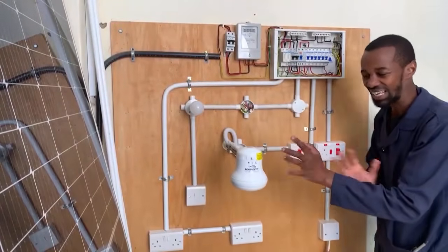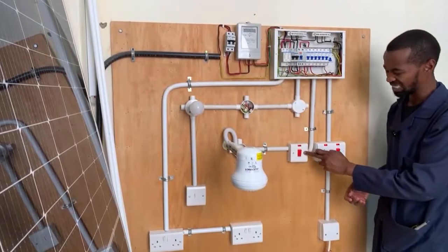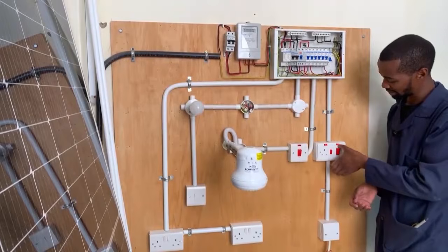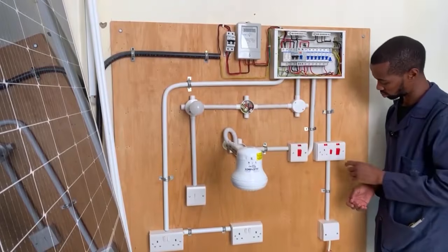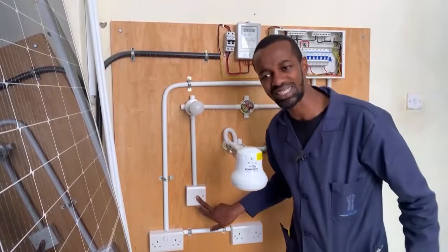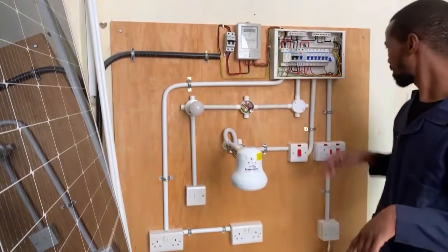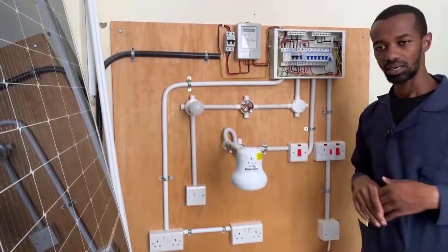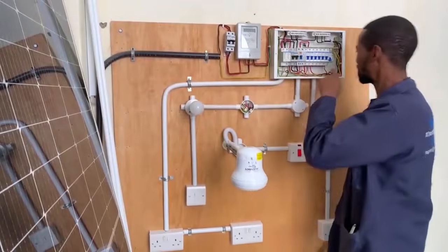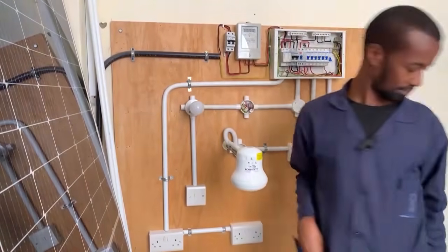This heater here is powered on. You can see that light. I don't know whether you can see it. It is on. This cooker socket here, or the cooker unit, is on. But the light here is not turning on. Those are some of the very important questions that you ask your customer. So the MCB is down. Now, once you visit the customer, you have seen that the MCB has tripped. You start troubleshooting. All right.